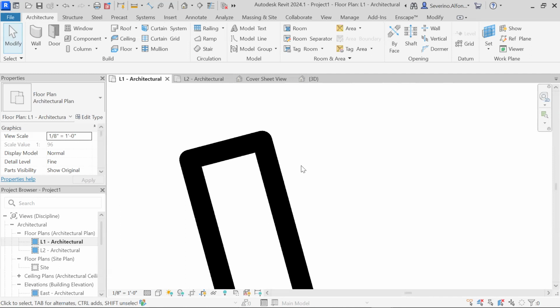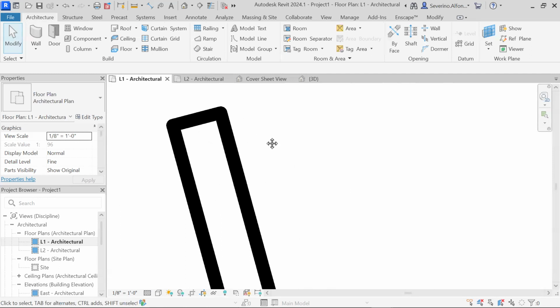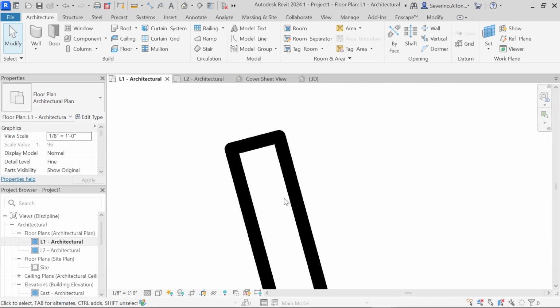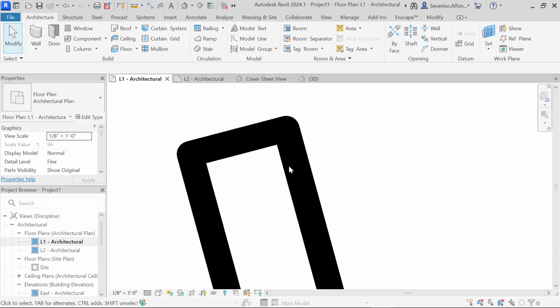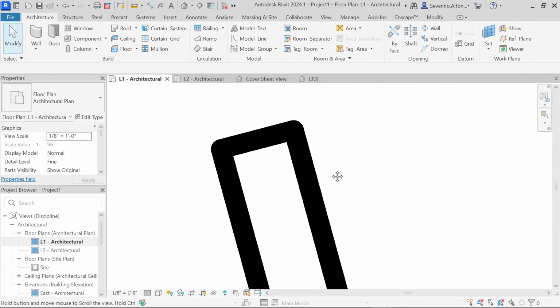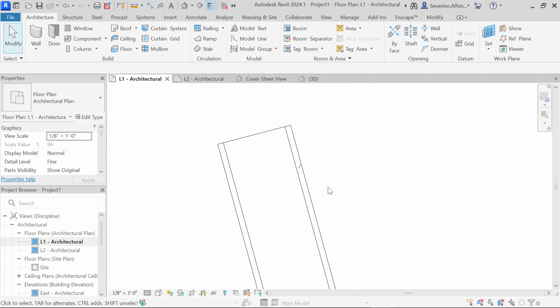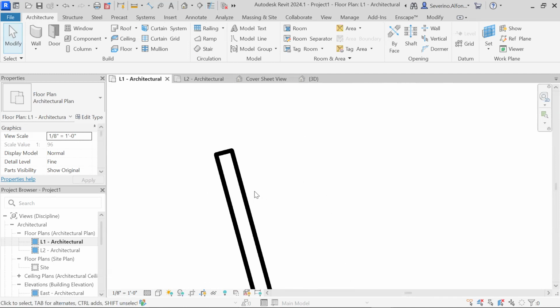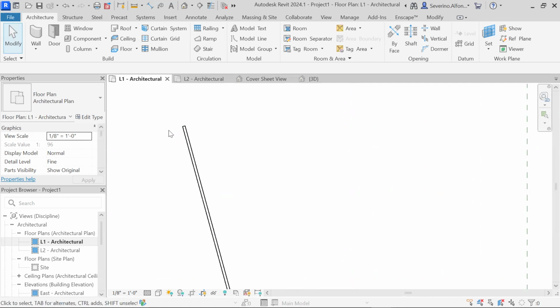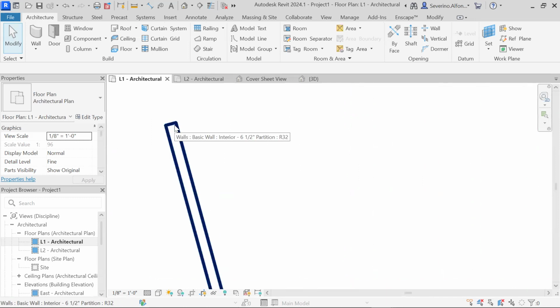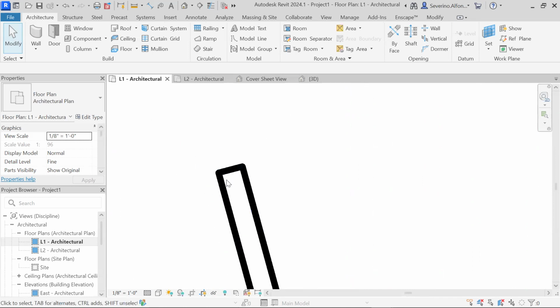So that's the way shortcuts work in Revit. Thin line is important because oftentimes at a specific scale of 1/8 inch to 1 foot, the lines are too thick to see anything. So I typically go TL, see, oh, okay, that's good, TL back. It's important to keep it like this because what you see in Revit is what you get when you print. So this is as thick as you're going to see it later on when you print your PDFs and so on.